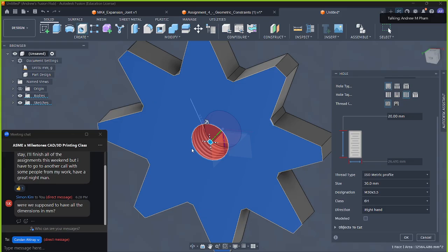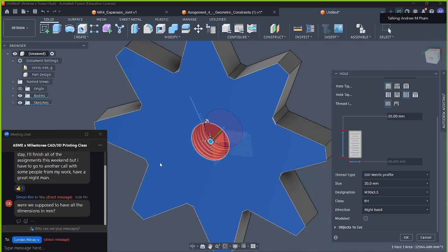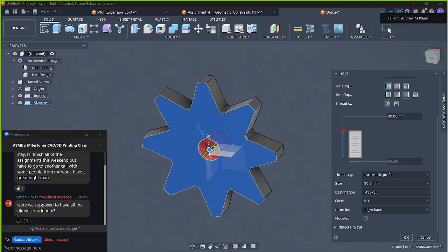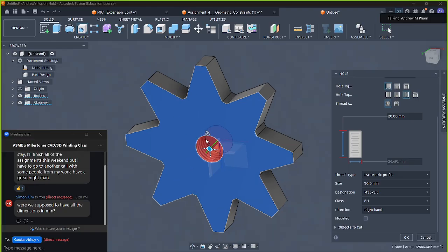So when it comes to part drawings, you'll click on a hole that you created with the hole tool, and it'll say exactly what it is, right? It's like, oh, use this drill bit of this depth, or tap to this depth, or something like that. Whereas if you just use a sketch and an extrude, you're going to have to do all of that manually. So using the hole tool can definitely save you time if you're making part drawings, and it eliminates a lot of work and it communicates a lot more information.